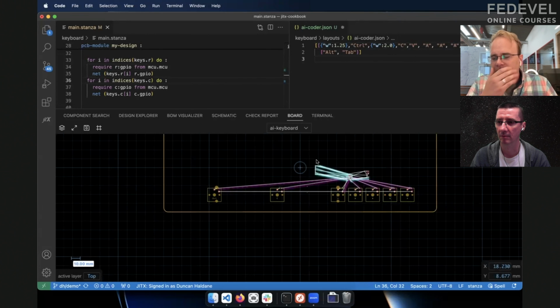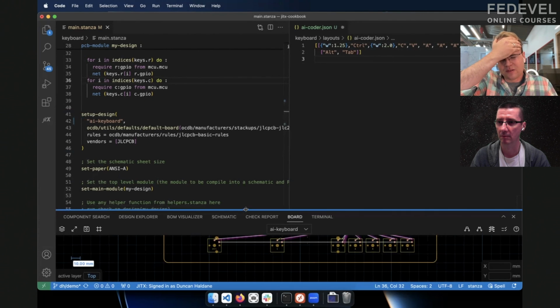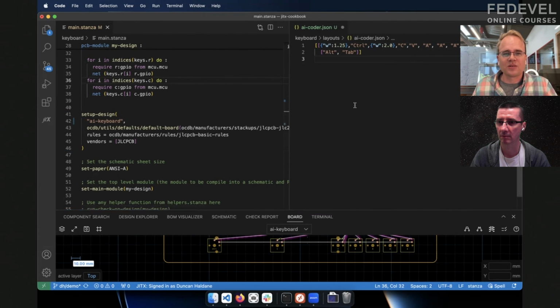But yeah, anywhere you've got standard data, like 100-page PDFs of VPX backplane standards, for example, there are really rich domains for automation here, especially large complex components with a lot of regularity, like an FPGA or a processor. Honestly, writing the importer to bring that data in systematically and then creating the design is faster than just drawing it, because of the amount of work and rework you have to do to create the design, improve it, and recheck it. You find it crosses that usefulness threshold pretty quickly.